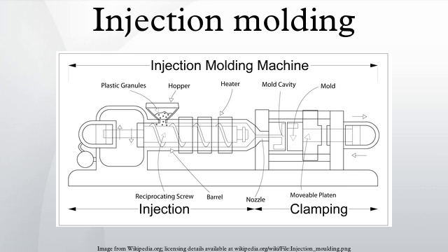The standard method of cooling is passing a coolant through a series of holes drilled through the mold plates and connected by hoses to form a continuous pathway. The coolant absorbs heat from the mold and keeps the mold at a proper temperature to solidify the plastic at the most efficient rate. To ease maintenance and venting, cavities and cores are divided into pieces, called inserts, and sub-assemblies, also called inserts, blocks, or chase blocks. By substituting interchangeable inserts, one mold may make several variations of the same part.